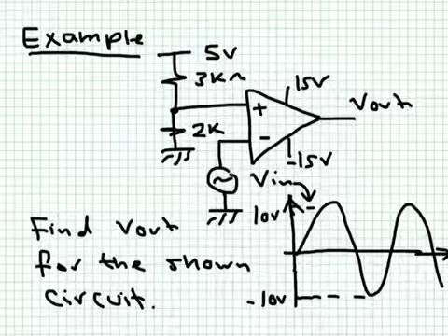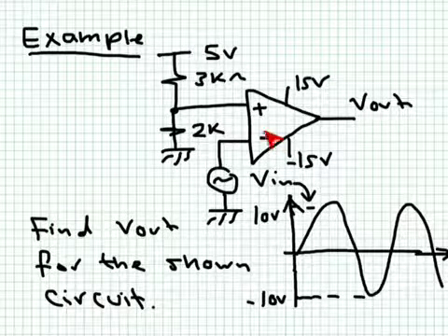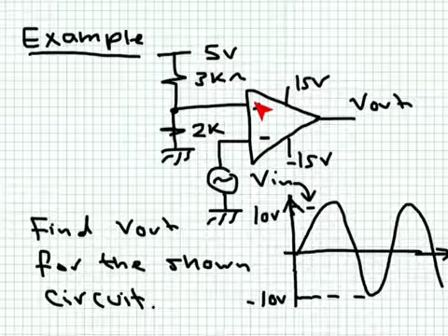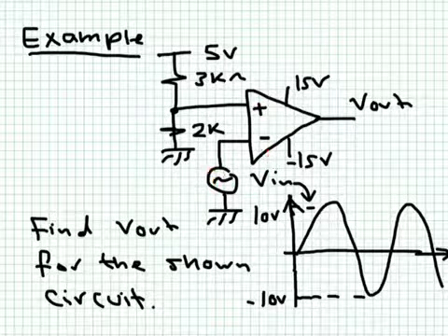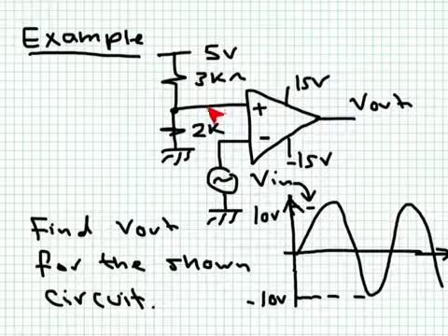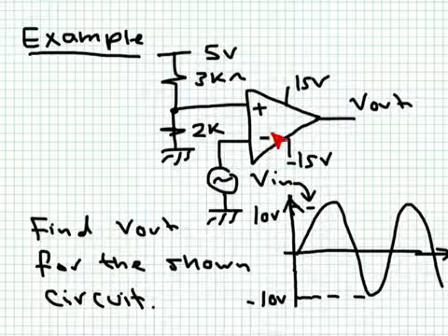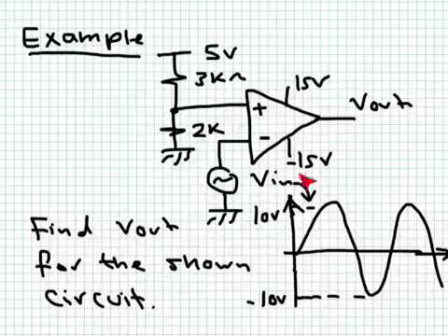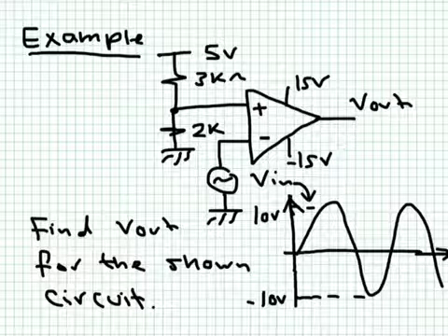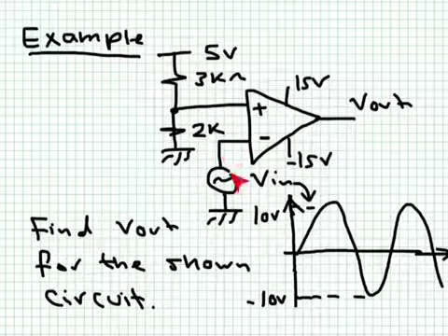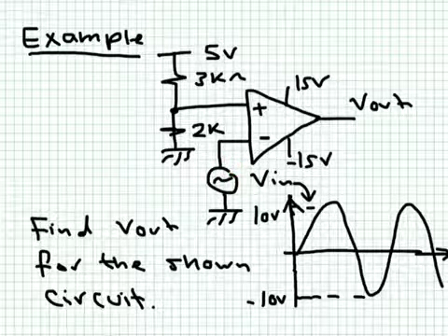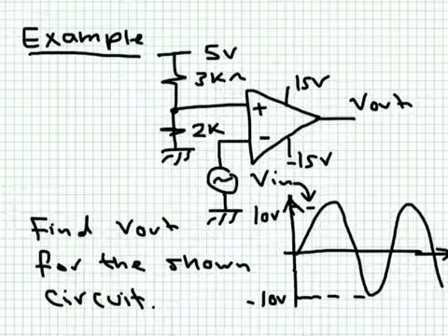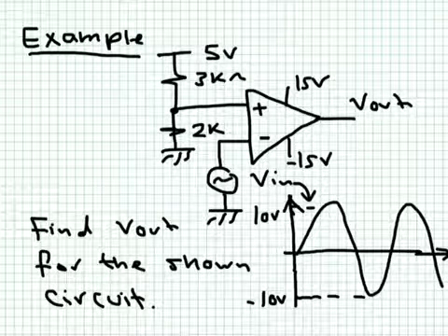So what's happening is very simple. Remember here, I'm connecting the input to the negative terminal, not to the positive terminal. So I'm comparing V negative to V positive. When the input voltage exceeds the Vref, the voltage here, then the negative terminal will have a higher voltage than the positive terminal. Then the output will saturate at minus 15 volts. Remember, I'm applying the input here to the negative input terminal, not to the positive input terminal as in the previous figures I've shown you. I picked this one specifically different to show you the difference.